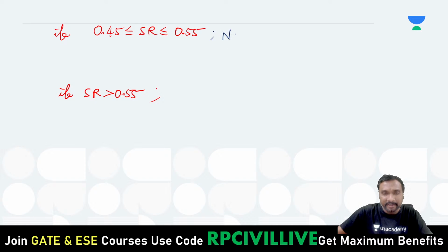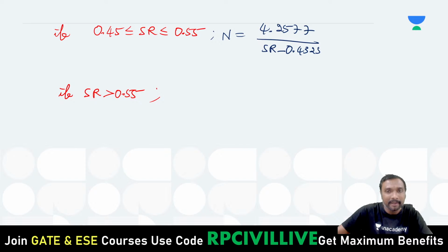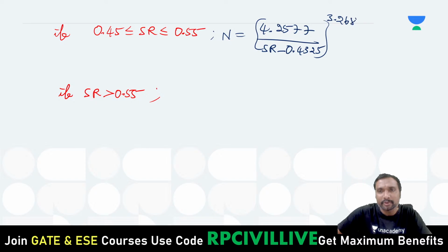That fatigue life N is equal to 4.2577 divided by the stress ratio minus 0.4325, whole power 3.268. That is your fatigue life, right?